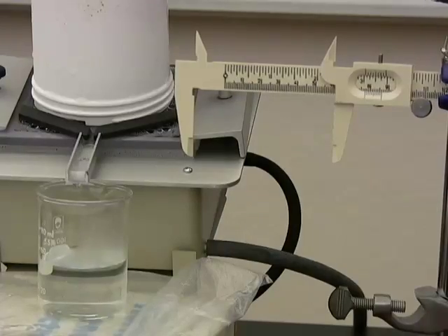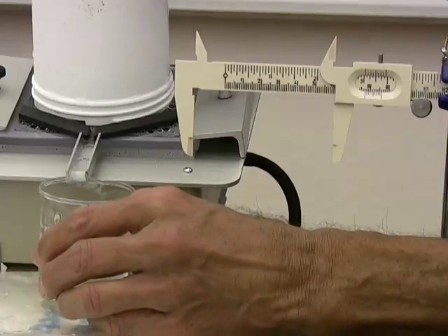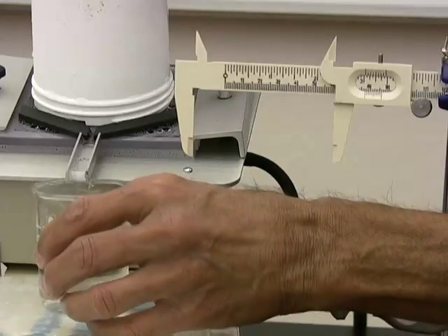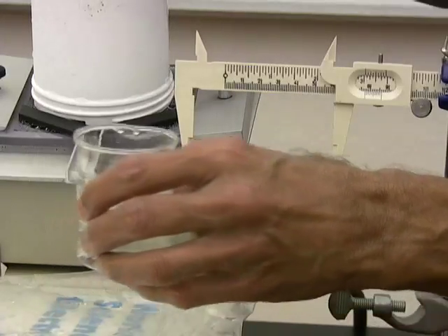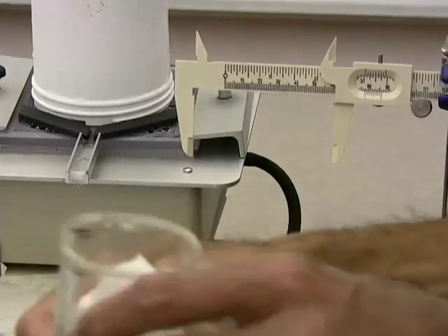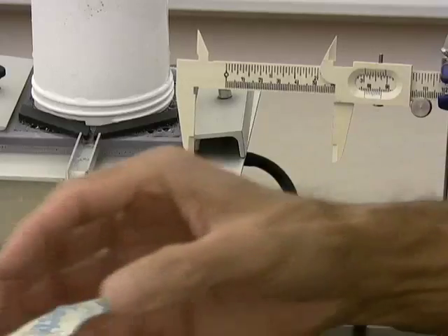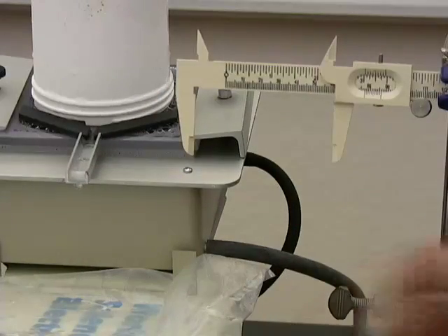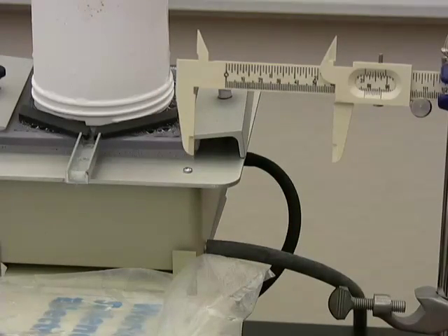Well, I have now collected water for 10 minutes. The mass of water melted due to ambient heat as well as heat conducted through the material. So measure the mass of this water and calculate the uppercase M for the material Lexan.